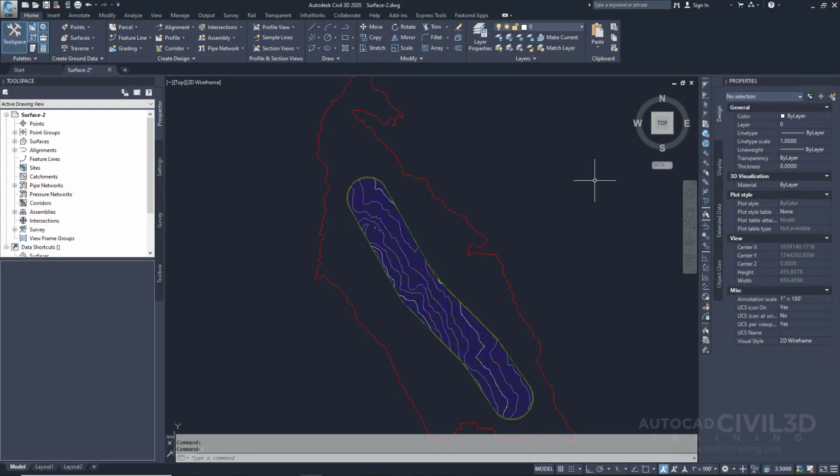In this exercise, you will use the point removal method of simplifying a surface. This method randomly selects points from the surface and reduces them based on the point density at different areas of the surface. More points are removed from areas in which the concentration of points is very dense than from areas that contain fewer points. Now note, you can't specify which points to remove.